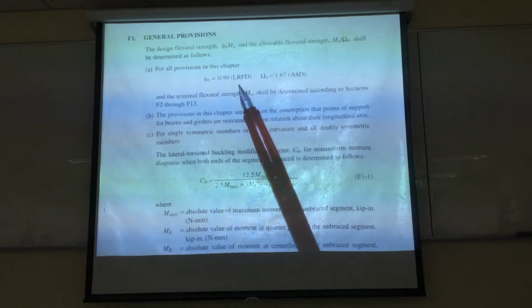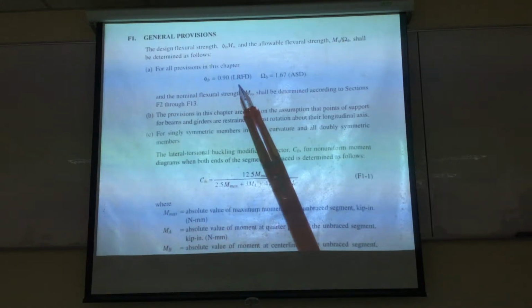It says, for school, for residences, for public area, for the car park. Car park is just so general. Sometimes you have no idea, if I have a truck parking or some other kind of parking, which one should you go for? But ASCE 7 is always updated, and it includes so many cases for the live load.